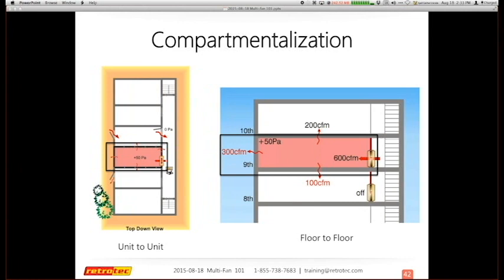All right, the next one I want to talk about is a compartmentalization test. This is something that LEED does. Of all the tests, I feel this has a much higher priority than just testing the entire skin of a structure, because I ultimately am testing the skin or the outer air barrier when I do this, but I'm going to do it on an individual basis. This is what allows me to control connections between units on each side, above and below, or floor to floor, to find out where my smoke or fire issues are, or what other kinds of contaminants may be moving throughout the structure or to my neighbor on each side.